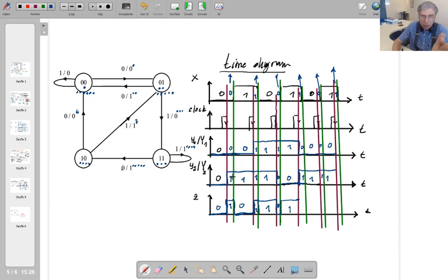So in between, my state changes, but my input hasn't changed; it stays as the previous input. In this case, what happened is an output that I don't want to see. Why is that? Because my expectation is this: there is a state, you apply an input, you come to a new state, and then you're going to apply a new input. But we cannot do it. We came to a new state, and still we've got the previous input.